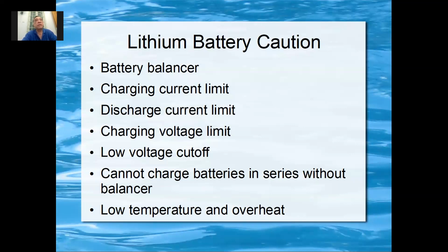So guaranteed one will be fully charged, the other one will not. And over time, the one that's not fully charged will get less and less charge. So it's not a good idea to connect like that. But if it's lead acid battery, you can just put 2 together, you can charge them in series.